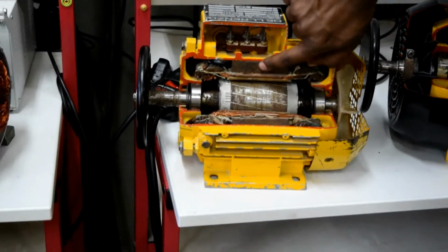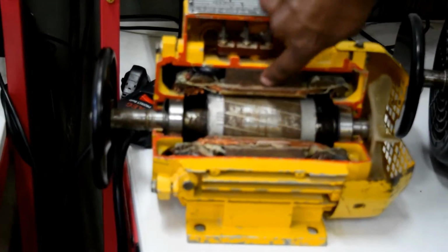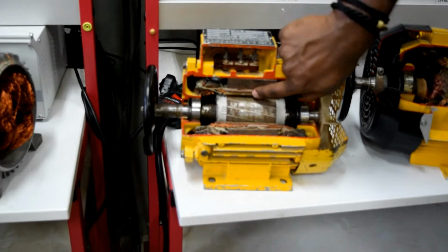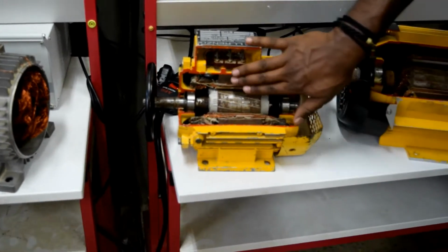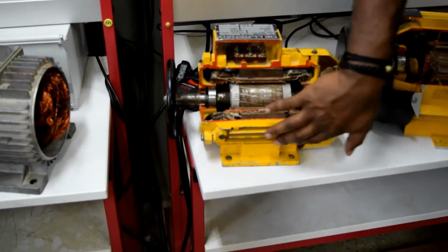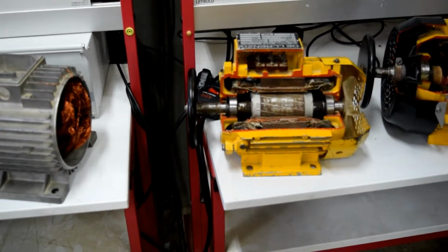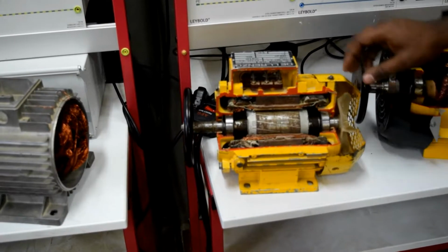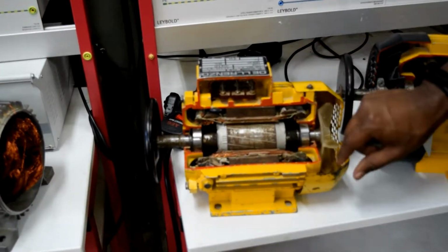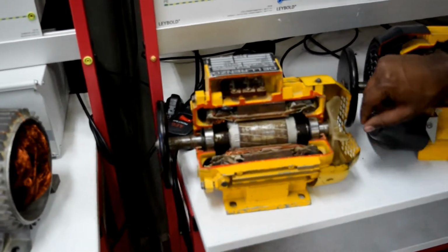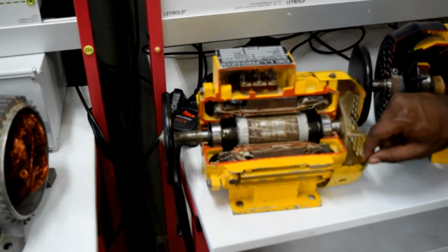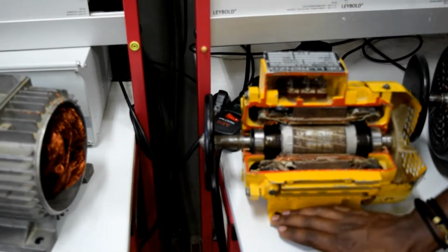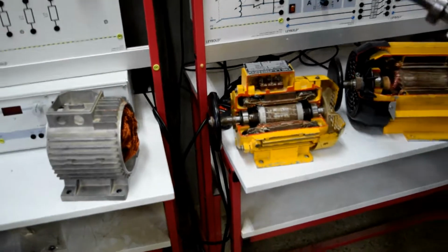So here we have the stator. This one is the main pole with the main winding. Together they are used for producing the main magnetic flux. And then the mechanical part, we call it a frame, which is used for protecting the machine from damage. And then here we have a ventilation shield. This ventilation shield is used to protect the ventilator from damage. And this one is a basement, used to attach the machine to the other mechanical device.